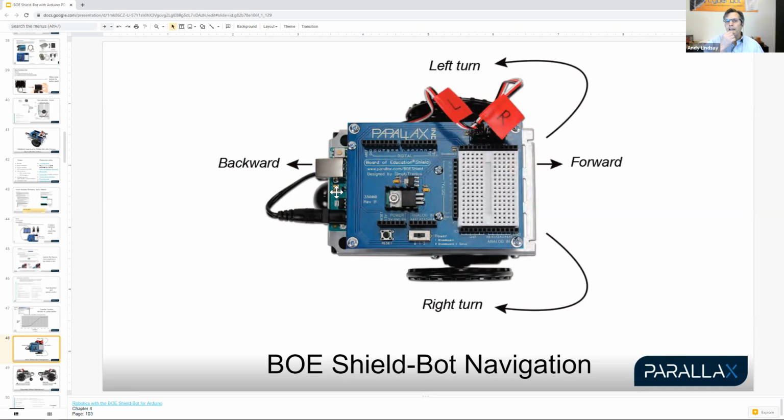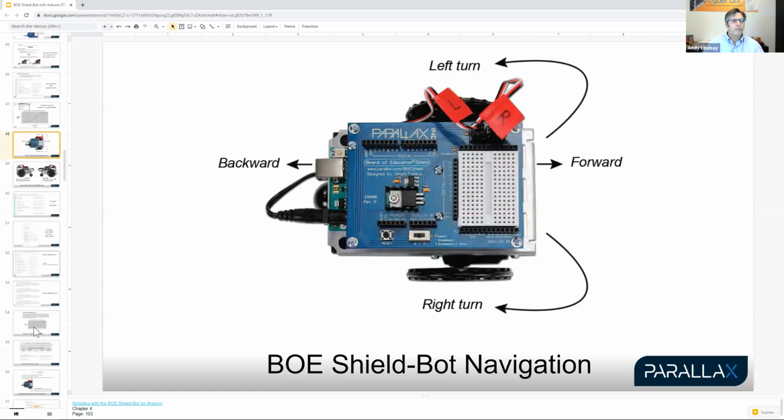If you have it backwards, if the breadboard is hovering right over the tail wheel, all you have to do is pop out the 4 screws on the corners and pull it up, give the board a 180-degree turn, then put it back on with those 4 screws. It's very quick, and if you have it that way, I recommend doing that as soon as possible. As in, if you have it the way it's shown in the picture here, great. If you have the board on backwards, unscrew those 4 screws, give the board a half turn and put it back on.